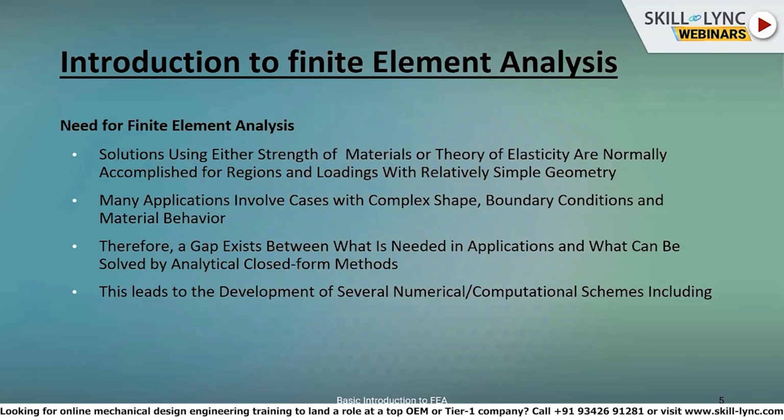We can get that information by using solutions from strength of material or theory of elasticity, which are normally accomplished for regions and loadings with relatively simple geometry. But we can use that only for very simple applications, because it is formula based and those formulas are applicable to simple geometry.